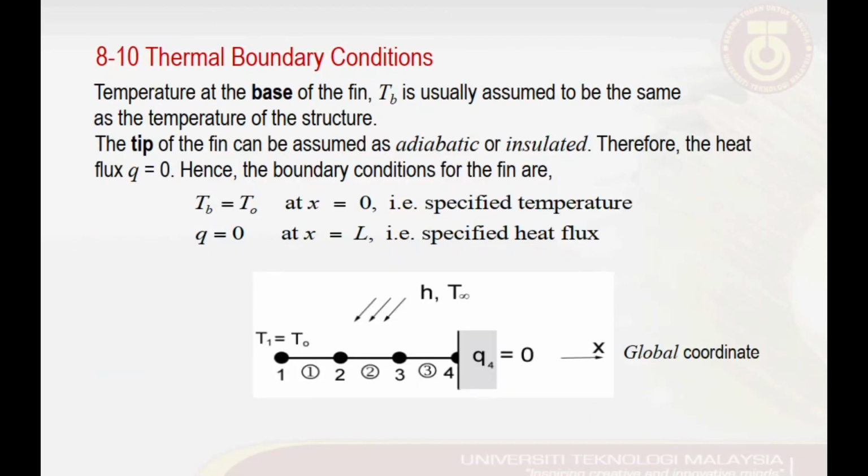Now let's look at the thermal boundary conditions. As I mentioned just now, solving the system of linear equations requires us to specify the boundary conditions. The first boundary condition is in the form of the known temperature at the base. The temperature at the base of the fin, usually referred to as TB, is usually assumed to be the same as the temperature of the structure.